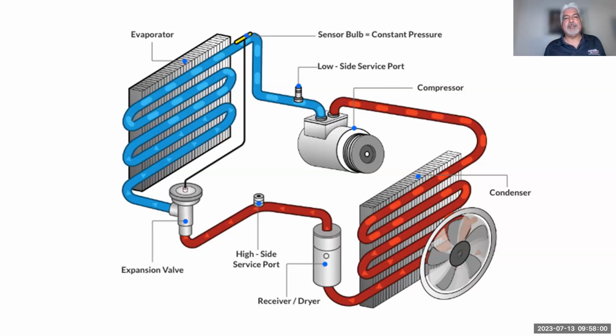But in this case, the problem is, where's the leak at? You're trying to find the leak. Obviously, you want to look at fittings, the front of the compressor where the clutch mechanism is at. You can have a front seal leak on the compressor, around the manifold fitting, or combination fitting that goes on top of the compressor. That could be the leak.